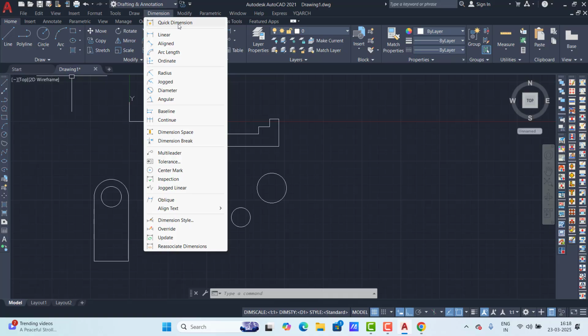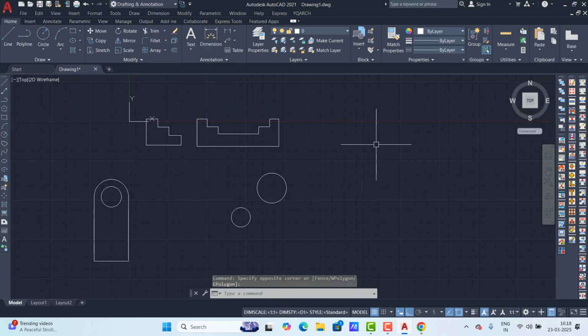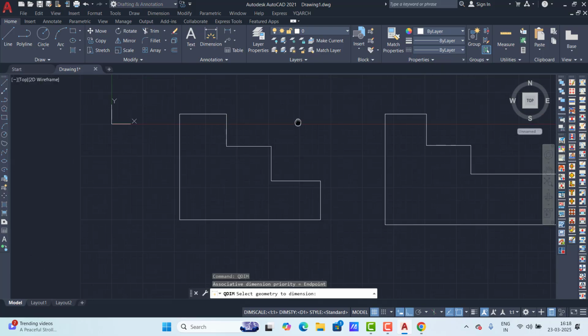If you want to present this radius in a different style, just go here and select this style. So this way, if we add different styles, anytime we can switch from one style to another. So this is a different style, this is a different style. If you don't put dimension styles and you use only Standard, you can present only one style in dimension.